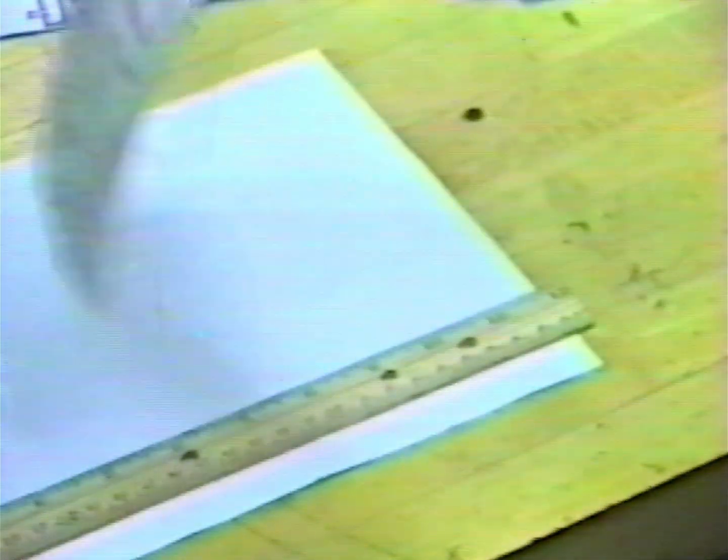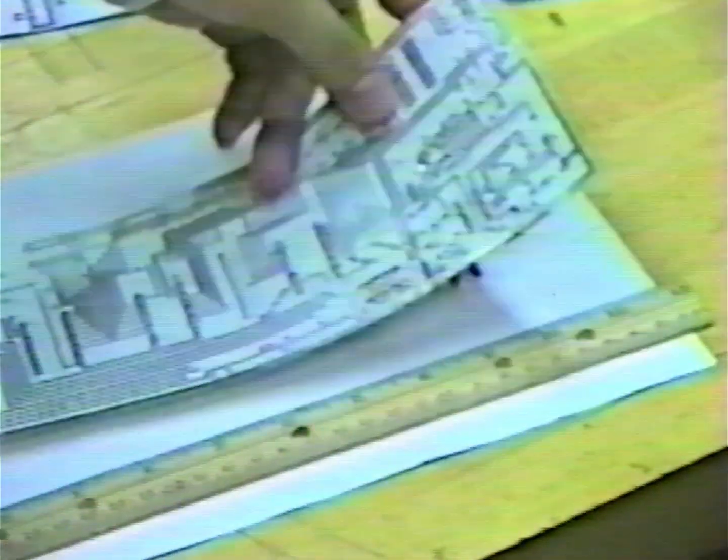This part of the tape shows experiments with three-dimensional robot motion planning using the infrared sensitive skin developed in our laboratory. This is the skin before the installation on the arm and before infrared sensors, about 500 of them altogether, are placed on it. Three such boards are used in the sensor system. As you can see, the printed circuit material is quite flexible and can be easily bent.